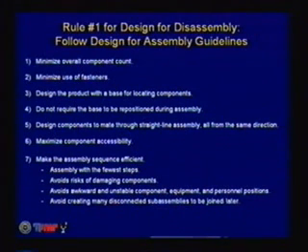Minimize the number of components, integrate components that are made of compatible material, and minimize the use of fasteners. You have to disassemble those too, and for disassembly they can rust and be even more difficult to take apart if we're talking about threaded fasteners. Don't require the base to be repositioned; the more effort it takes to reposition something, the longer it's going to take. Maximize accessibility, that's obvious. Use straight line assembly and straight line disassembly, so you don't have to reposition. And try to minimize the number of types of tools you're using.